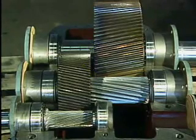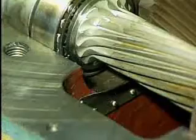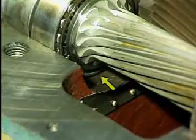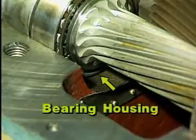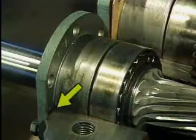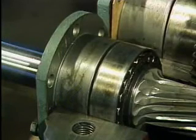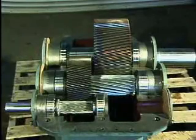The pinions and gears are mounted on shafts, which are supported by bearings on either end. The bearings are supported in parts of the casing referred to as the bearing housings. Spacers, or shims, are placed between the bearing housings and the end caps to properly position the bearings, shafts, and gears inside the casing halves.